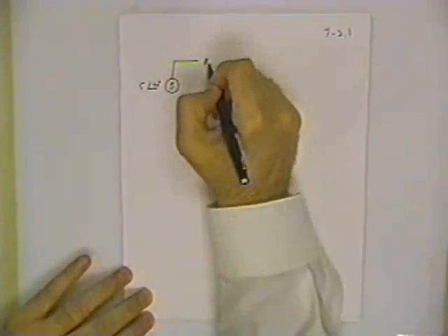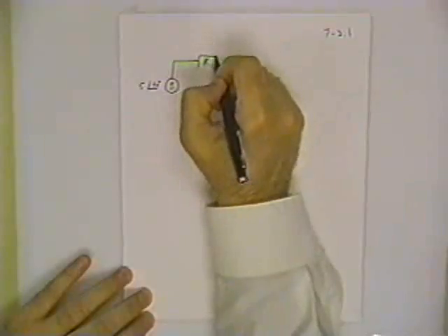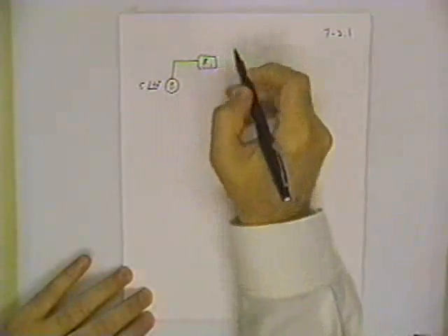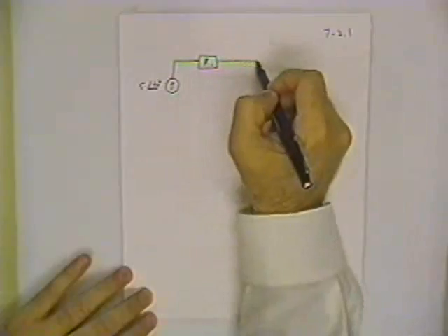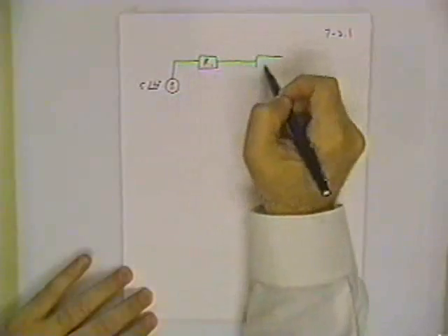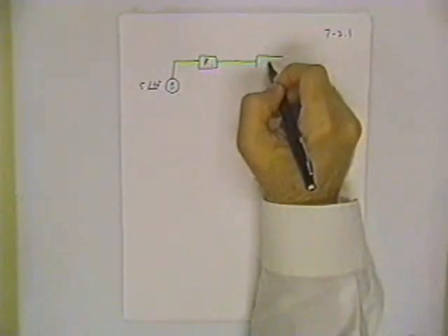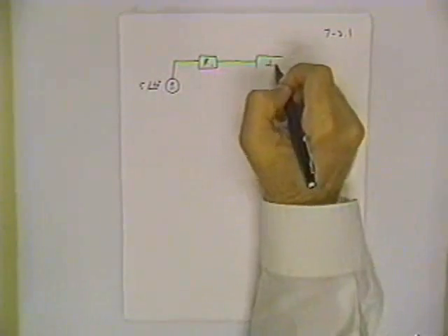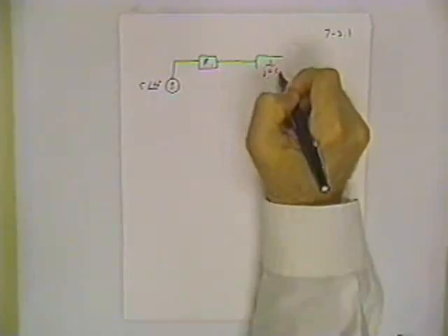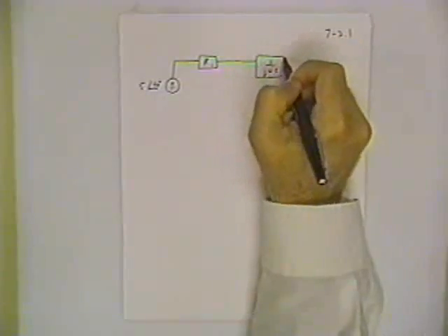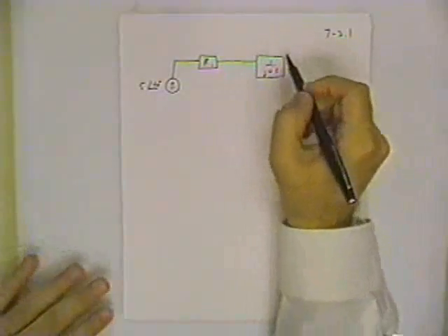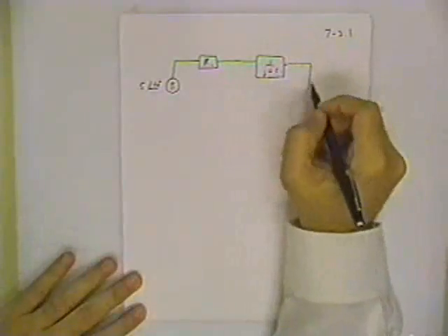Okay? And you have R1 is a numerical value of the resistance. That becomes the impedance for that resistor R1. For C1, we're going to put in the complex number, or the pure imaginary number, 1 over J omega C1. And so on around the circuit.